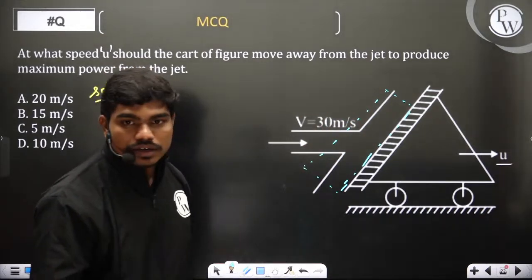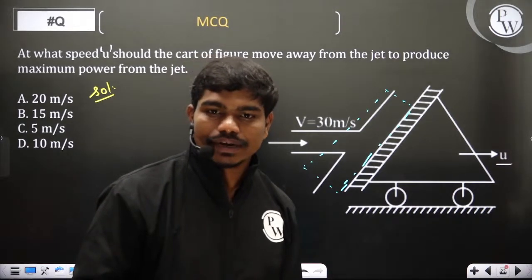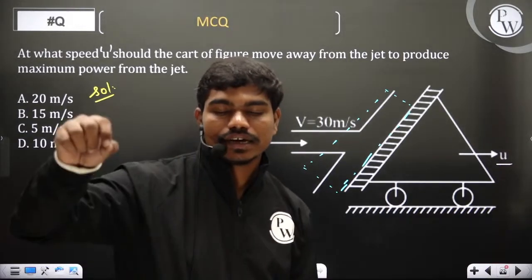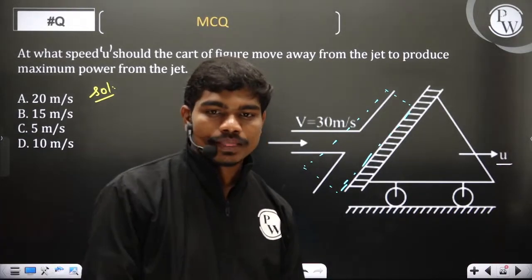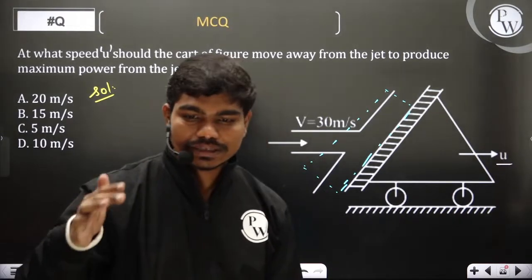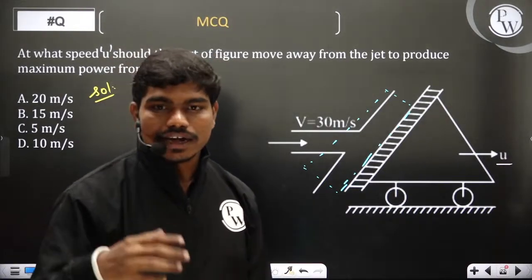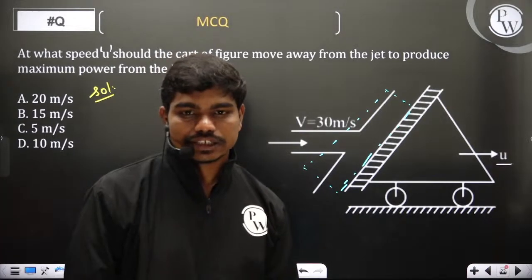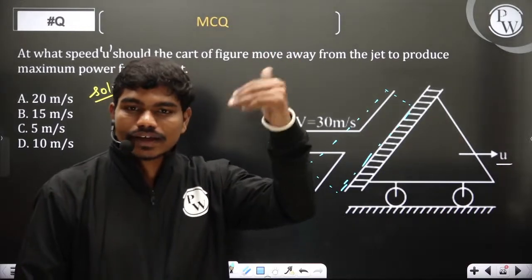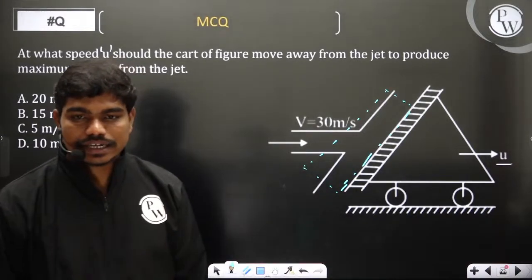Okay? Now, in case of rocket, reduction of mass or volume helps in increasing the velocity of escape. It happens, okay? And also we will plan the combustion accordingly, so that the combustion rate and combustion stages are planned accordingly. Normally within the atmosphere, we will try to maintain the less velocity. We should reach escape velocity, but we will try to keep maintaining the less velocity because atmosphere exerts a drag on the rocket, and drags beyond certain levels can actually affect the materials. So that's what we'll see. As we go high, we keep on accelerating because the atmospheric drag reduces. We'll see some important discussion in compressible flows regarding this.